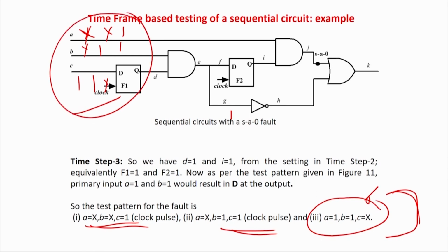So the computation has been done by the ATPG tool, and it has told me that these patterns have to be applied. Now I am applying. One thing I think is very clear to you at present: if there is a scan chain, I do not require a 3-stage ATPG to do it. You have to appreciate that if there are 10,000 flip flops in the dependency list, or the depth is 10,000, then the ATPG will also have a 10,000-step ATPG in the worst case. So test pattern generation will be very, very complicated.